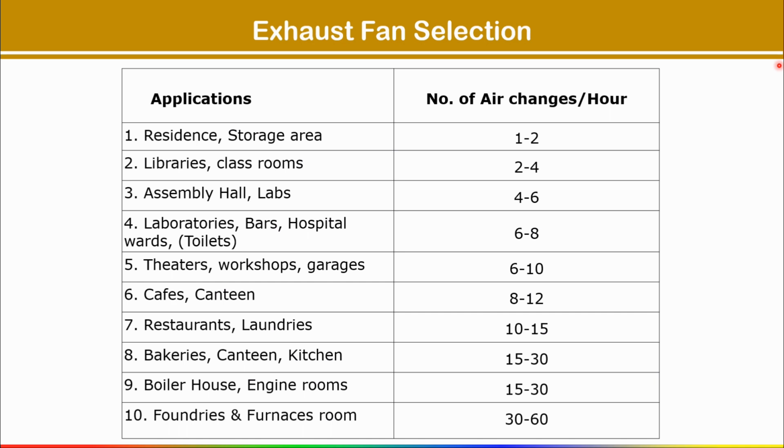So now here I am taking one question, so it will be easy for you to understand how we can find out the air discharge rate, because based on air discharge rate only you will get the fan model, size and noise level, everything from the manufacturer catalog. As a designer, our main target is to calculate the airflow rate, that is how much air we need to discharge or exhaust from this space.